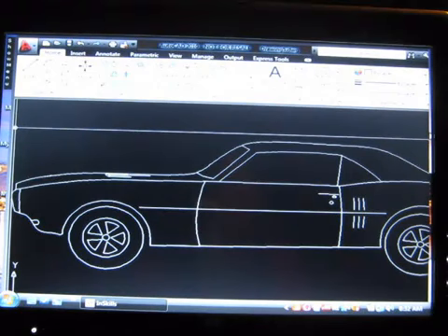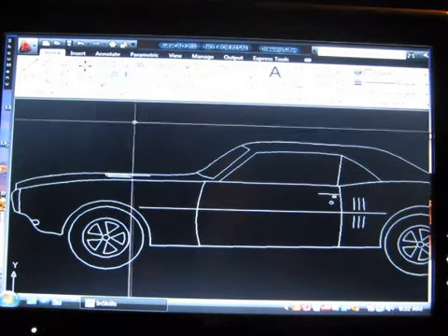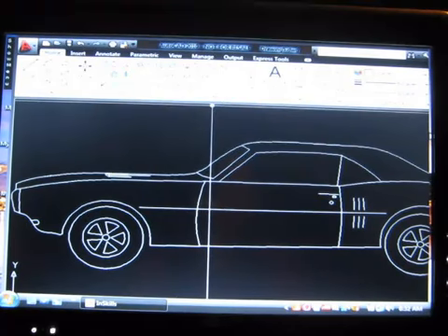There are 2 main spaces that you will draw in: model space and paper space. Model space is where your drawing objects go, and paper space is where your annotation and sheet objects go, like a title block or some notes. We'll cover those 2 spaces in greater detail in another section. When you move your crosshairs by moving the mouse, and you move them off of the drawing area onto, say, the ribbon area or one of these bars, the crosshairs disappear and are replaced by an arrow.